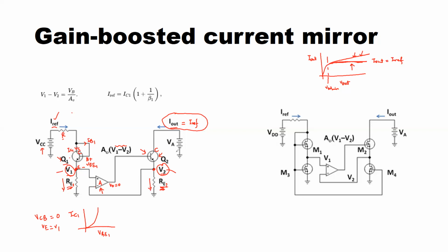Okay, now let us assume this voltage VA, which is connected to the collector pin of transistor Q2, goes up. It means the voltage at the collector pin of transistor Q2 goes up, so the current through the transistor, which is, let's say, IE here, goes up, increasing the drop across this resistor, which is nothing but your voltage V2.